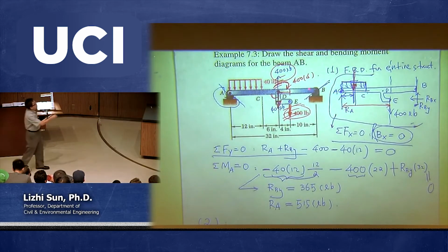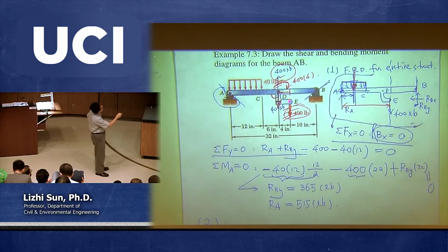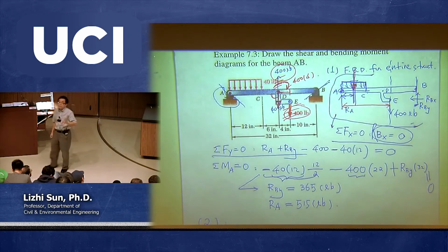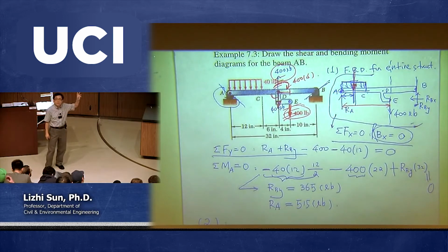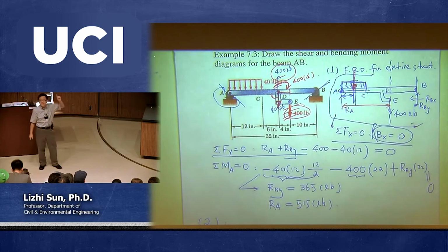So in other words, we're not going to plot the free body diagram, we're not going to plot the shear and moment diagram on this part. That's why we need to move this force to a certain point that is part of the beam. But you are saying, can I move point E to somehow this point? Well, in principle, you can do that. It's not a problem. But it will not help us to plot the shear and moment diagrams. Because in reality, this force is directly applied here through this kind of bridge. And that's why you need to choose that point instead of choosing point E.